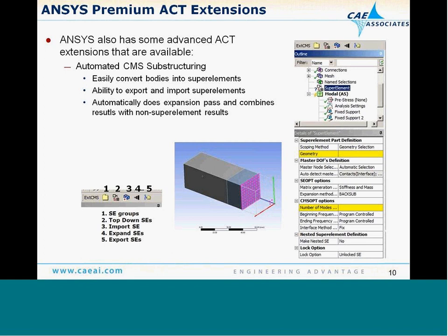Some extensions are not there, but they're ones that ANSYS has developed. This one allows you to do component mode synthesis in Mechanical. So you can create super elements from different bodies, and then behind the scenes it does a generation, use, and expansion path for those super elements. So it's a rather involved, call it a premium extension, but this was one developed for a particular customer.